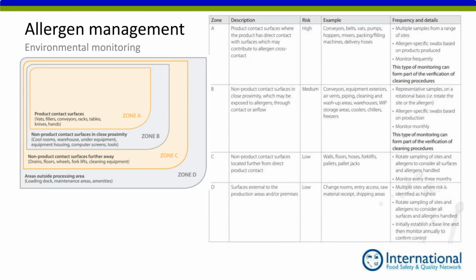allergen cross contact. So let's say, for example, that we have a feeder for the filling and we are producing pasta, and on this pasta line we have a filling with meat and we have a different kind of filling with cheese, but all of these fillings are going inside one same filler area, you know. So probably we will do some programs of allergen management where we start with the product that does not have allergens and finish with product that has allergens. We have some intermediate cleaning, etc.